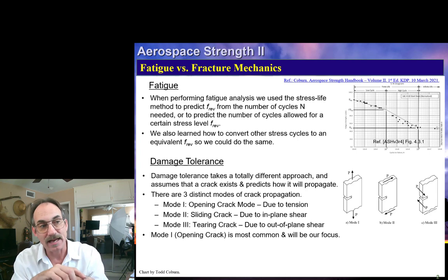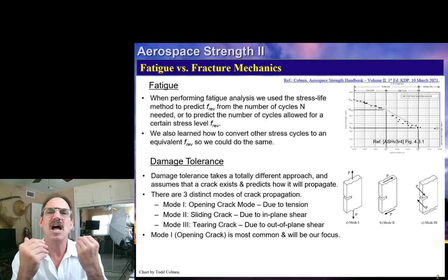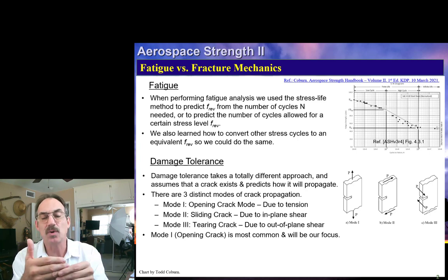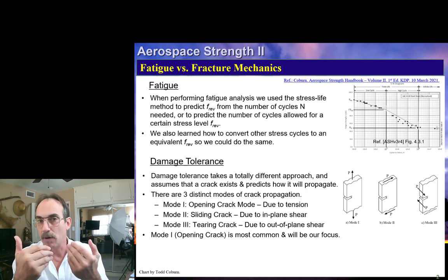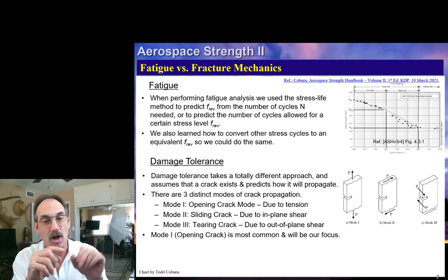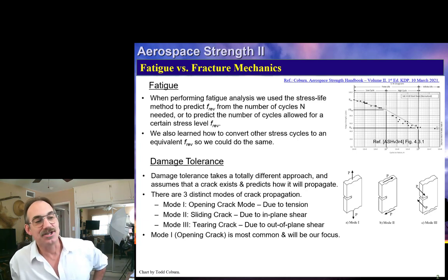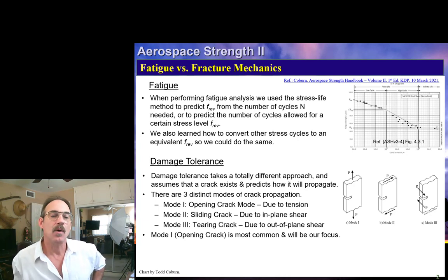Now, fracture mechanics is done for all these kinds of modes, but the most common one, generally the most critical and the one that's focused on mostly in aerospace, is this opening crack that we're calling a mode 1 crack. Okay, so that is going to be the foundation and the focus of our study here in this little introduction to fracture mechanics.